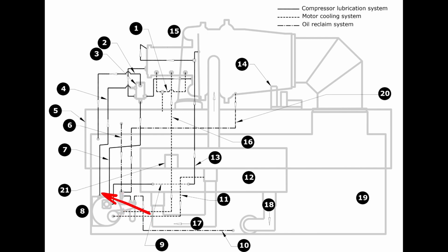So what we do is we have these vents. Some of this is going to depend on the generation of the machine, whether or not you have an oil separator, which vintage you have, how many vent lines there are, and even where that vent line returns back to. Some of the older machines did something different with a solenoid valve. The point is, we have a vapor vent that draws back into the suction side, or the evaporator side, of our system in order to take all the vapor that gets collected into our tank and distribute that out somewhere else in the system.